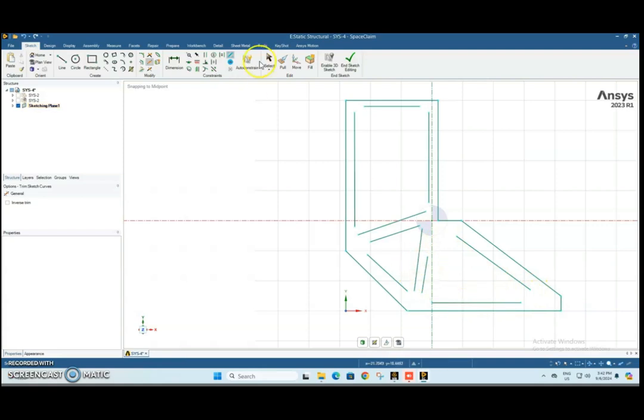All right, then we can go to create rounded corners. You can select here, then point to here, then enter 2 and click enter. It will help us create a 2 mm rounded corner. Same with this: you select this, point to here, enter 2, enter, and it will help us create this. We want to make all corners standardized, so you select this 2.